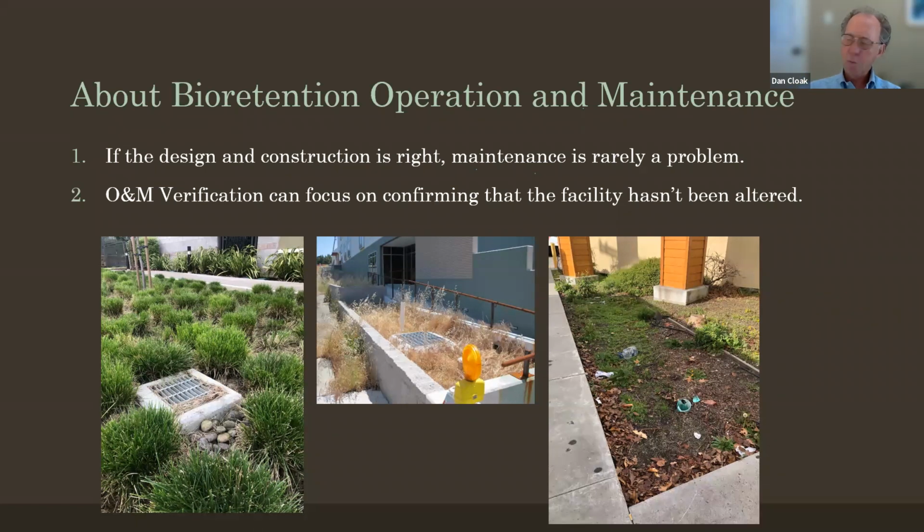And what you can see there, this was taken, I think, about 2-3 days after an approximately 5 to 10 year storm. And this facility is nicely maintained. There's nothing you can complain about it. But what I'm noticing on here is that the material that's shed by these grasses is accumulating on that grate right here. And so that indicated that during this relatively modest storm that a properly designed bioretention facility would have handled without overflow, this overflowed and some portion of the flow didn't get treated. Although I'm sure a lot of it did.